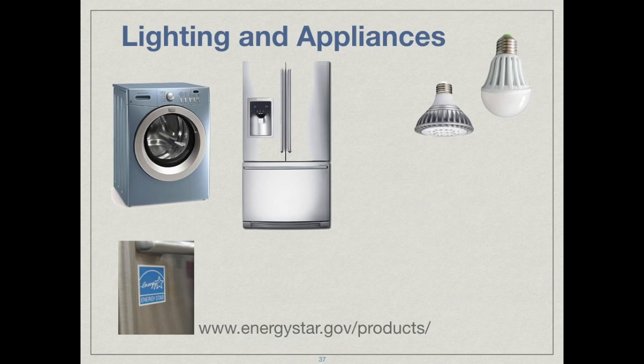The second thing is the color output of the light. It's called the color temperature. Most people like a warm color light in their house. That's more toward the yellow end of the spectrum. The warm white lights are what you commonly get from an old style incandescent bulb. But the cool white is more of a daylight, kind of a bluish color, and that can often be a little harsh for people.